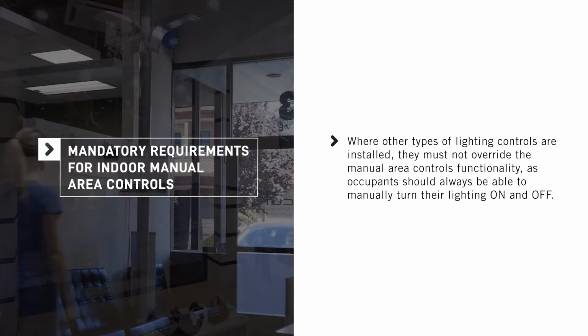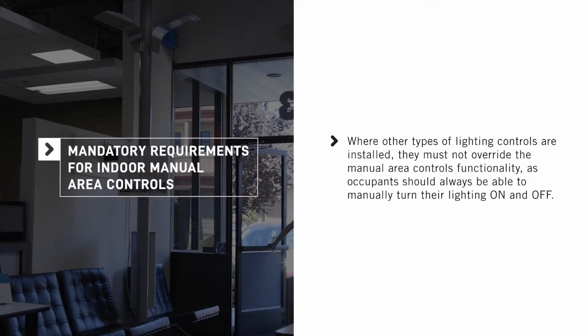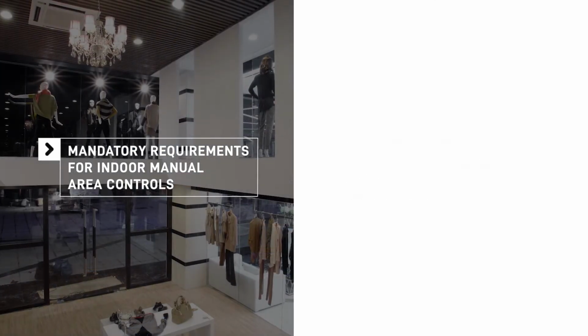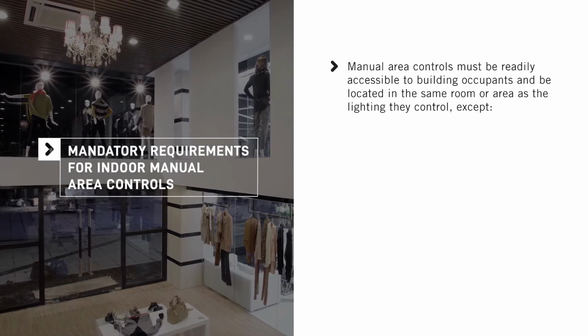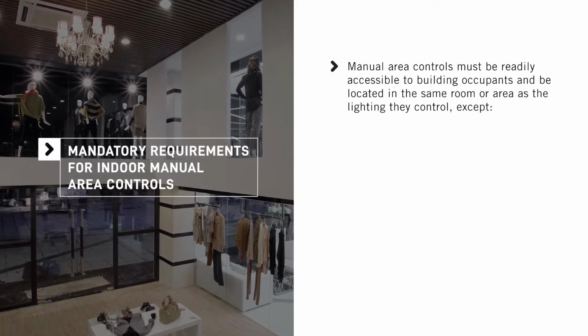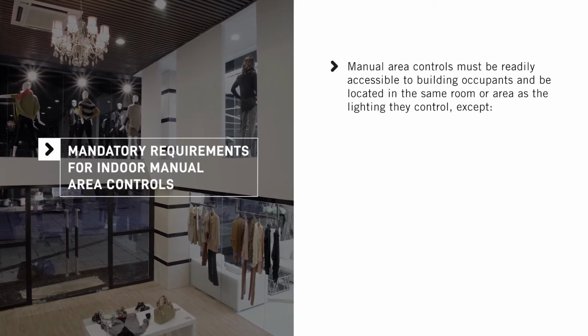In projects where other types of lighting controls are installed, they must not override the manual area controls functionality, as occupants should always be able to manually turn their lighting on and off. For most space types, the manual area controls must be readily accessible to building occupants and be located in the same room or area as the lighting they control.